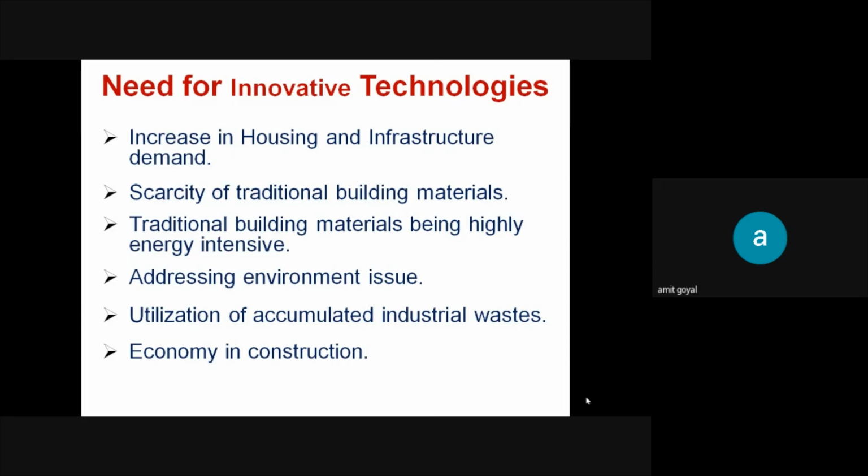So you can well imagine that if you can walk barefooted on the surface of the roof in a 45-degree temperature, that means the surface of the roof is not catching energy, and the heat is reflected, and my first floor temperature goes down, and I'm getting a ground floor temperature similar to the first floor also, right?